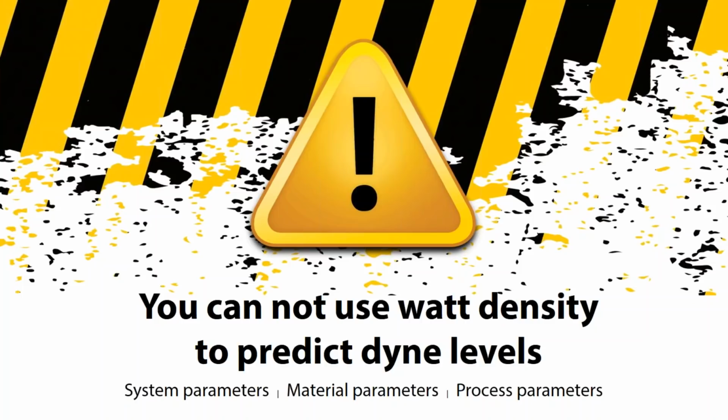A better approach would be to actually map or take your existing product mix and do a bit of qualification on some of this. On products you run regularly, maybe customers that are quite important to you, big jobs, big important products that go through your shop, you want to line up your watt density values, your dyne level values, and then your peel adhesion values all in a template.